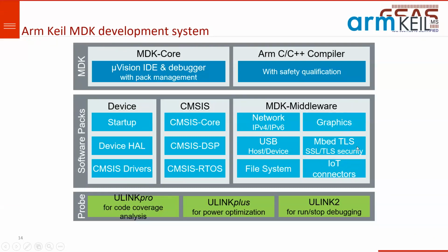So what does this mean? ARM came up with this specifically for IoT applications or wherever security is required. If you see that there is a threat of your data being hacked, that is when Mbed TLS tries to encode whatever data it sends in the packet. It will try to encrypt that data at the TLS level. Of the 7 layers of the OSI model, TLS is at the transport or session level. This is the level where the packets are actually formed.